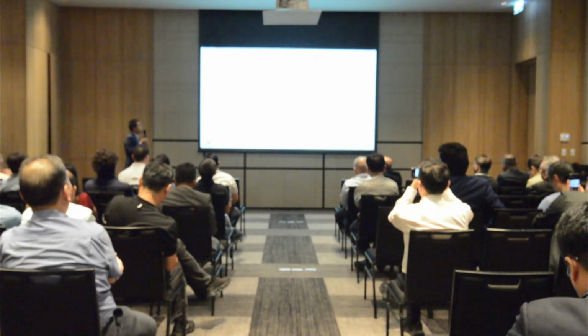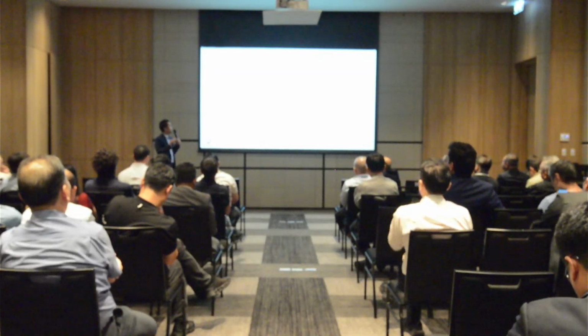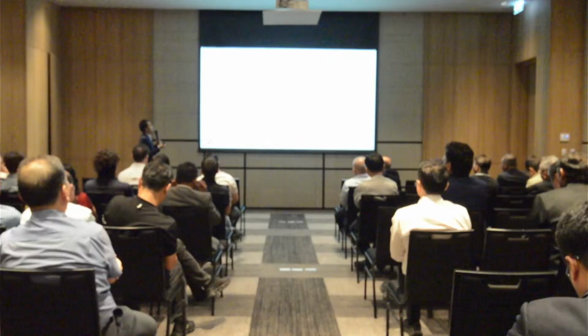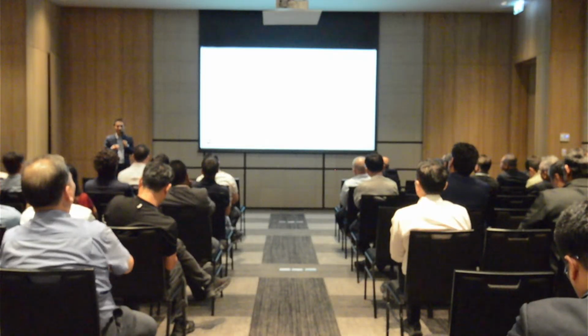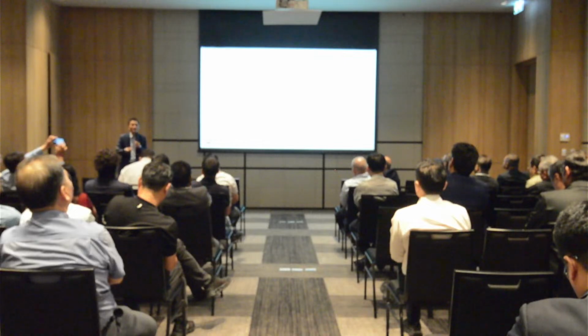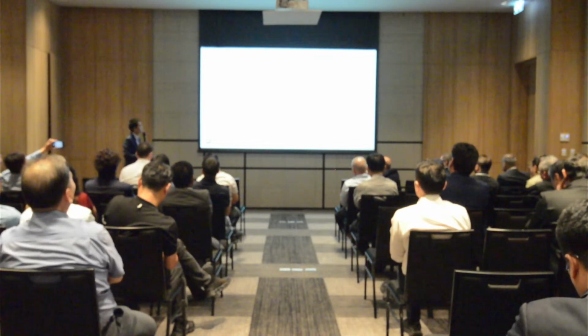And also, because our casting temperature is lower and the metal has less heat content, you will have less thermal fatigue. And then you will have a longer die life and reduced solidification time. You will get faster cycle time.